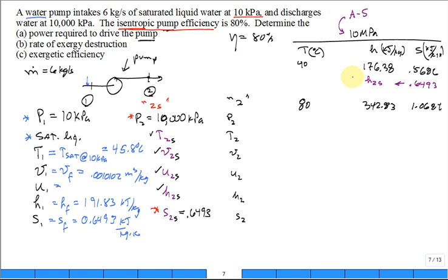So now you can also, for grins, find the temperature. Now I know that the purpose of it wasn't to heat up water, but it did heat up to 46.45. This is as good as your linear interpolation allows you to get, okay? This is the best we can do, linear interpolation in here. So what we find is this H2S turns out to be 203.23. So the enthalpy of the flowing fluid went from 191 to 203. Why did it go up?